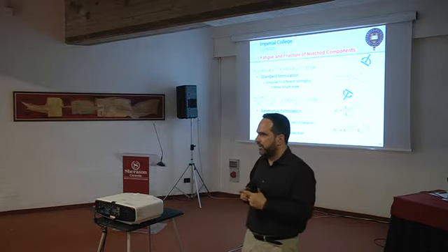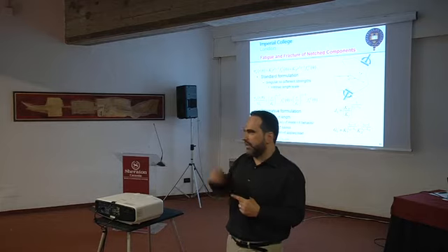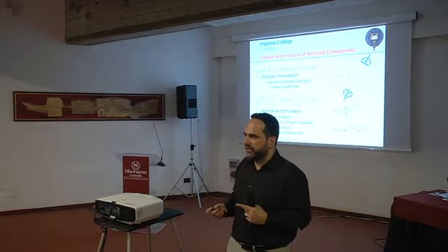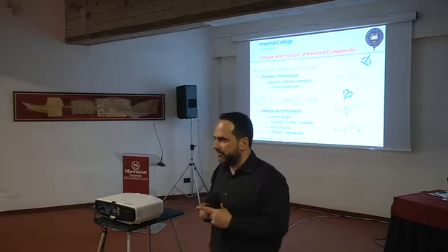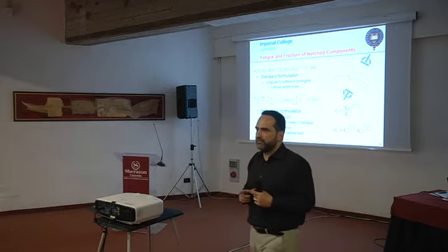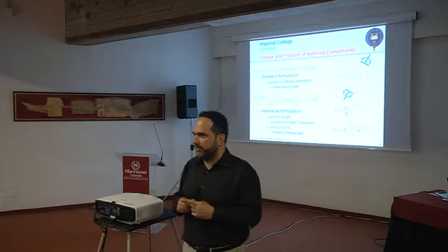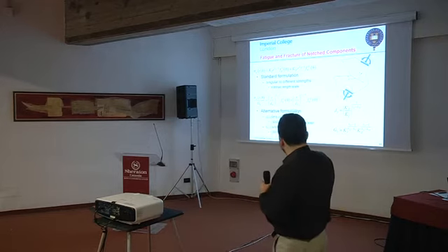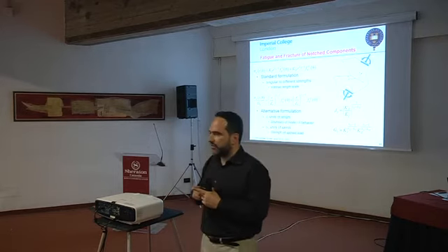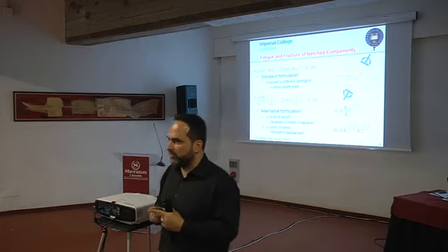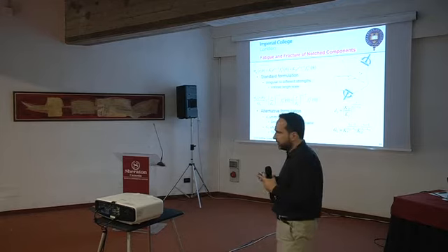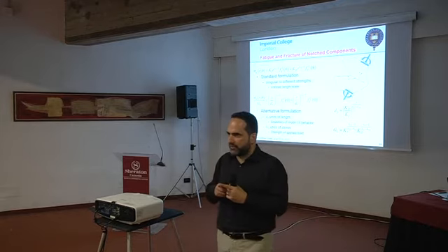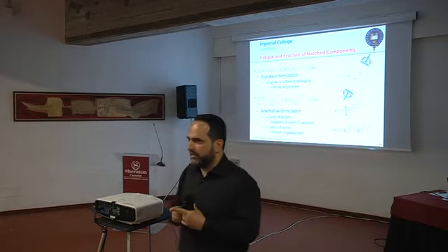Lots of people say, I want to do a test in mode 1 and I want to do a test in pure mode 2. Well, that is not as simple as just applying the load in a certain direction. You need to look at what the real state of stress is there and then try to understand which mode dominates. The only way to look at mode dominance is to look at the stresses, not at the load. What stress is dominating the solution is what your mode dominance is.